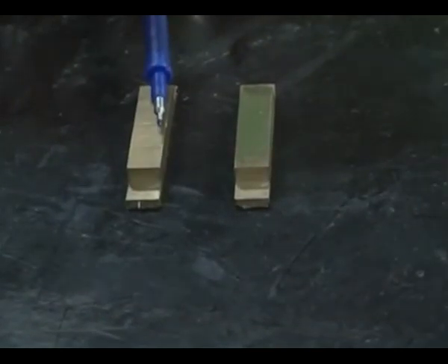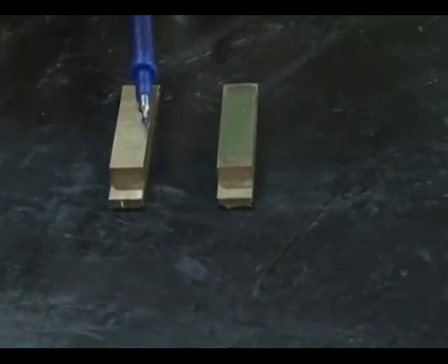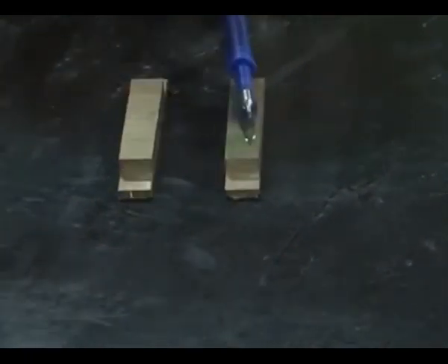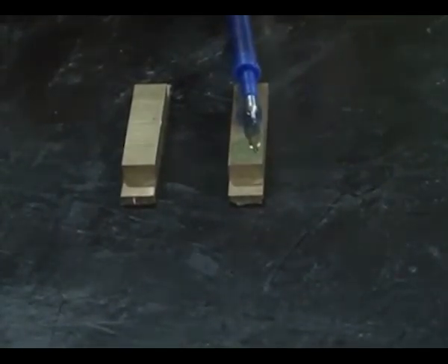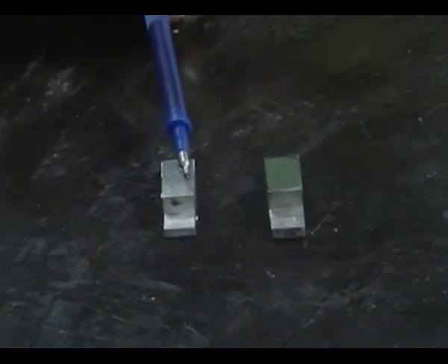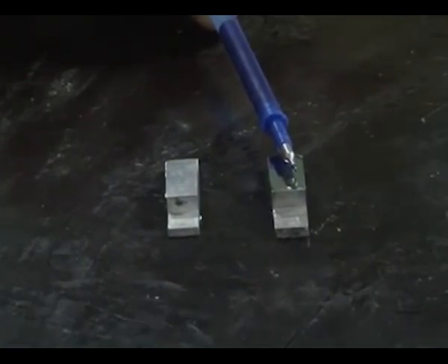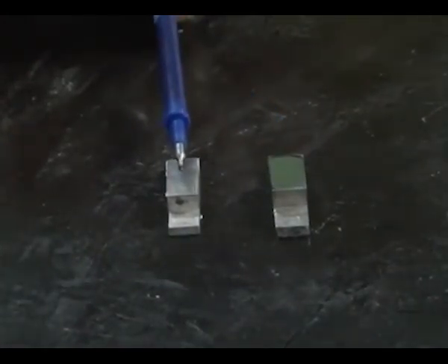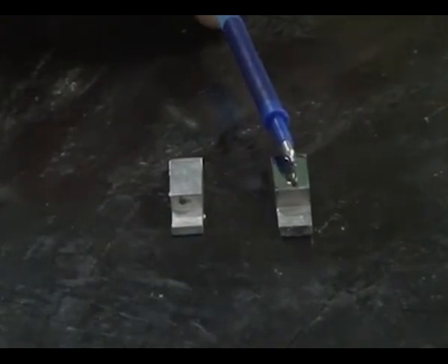You can see the initial workpiece of brass, wherein you can only see the shadow, but you cannot see any mirror image, whereas you can see the clear image or the mirror image in the finished surface by using the rotational abrasive flow finishing process or universal rotational abrasive flow finishing process. You can see the aluminum metal matrix composites, wherein you can find only the shadow, but after finishing you can see the mirror image clearly. This is the micron size surface roughness and this is the nano surface finish, wherein we have achieved the best surface finish of about 70 nanometers.